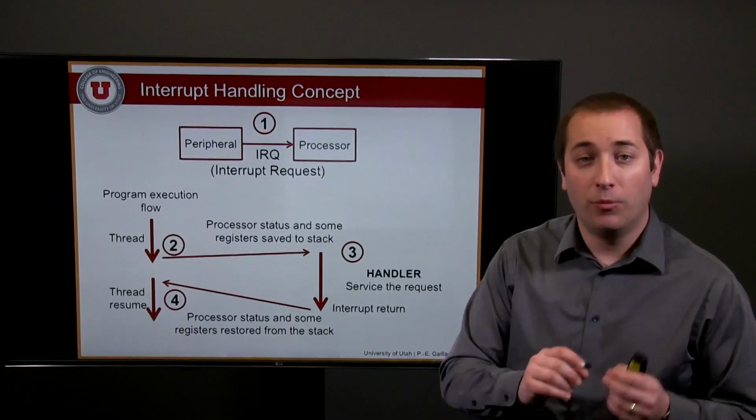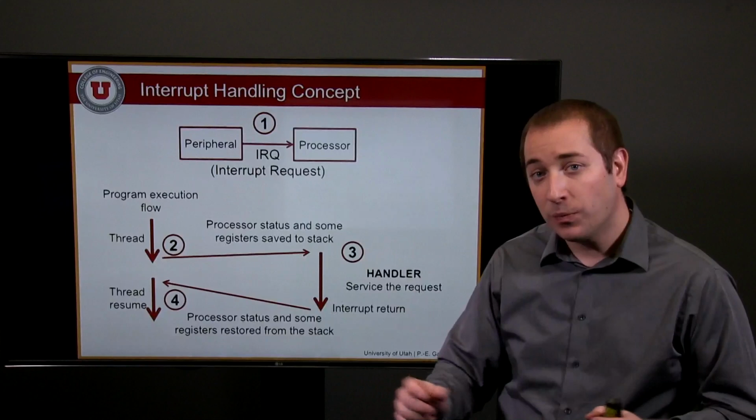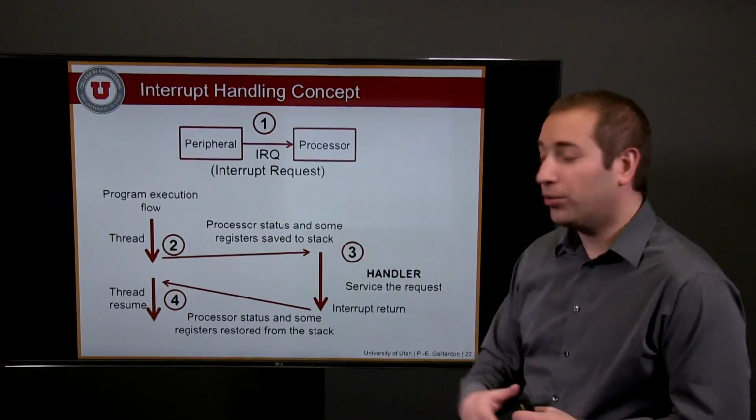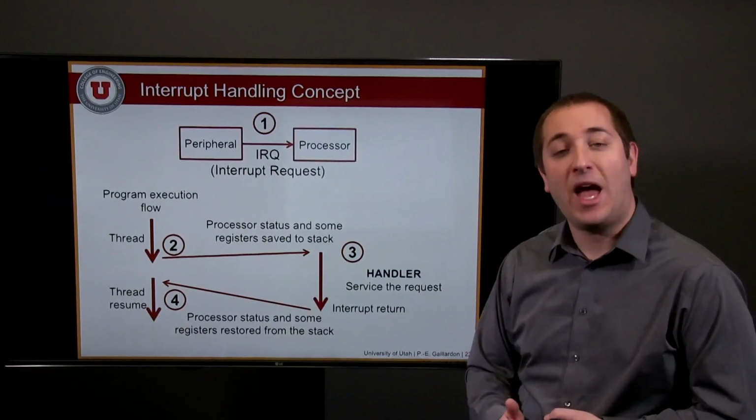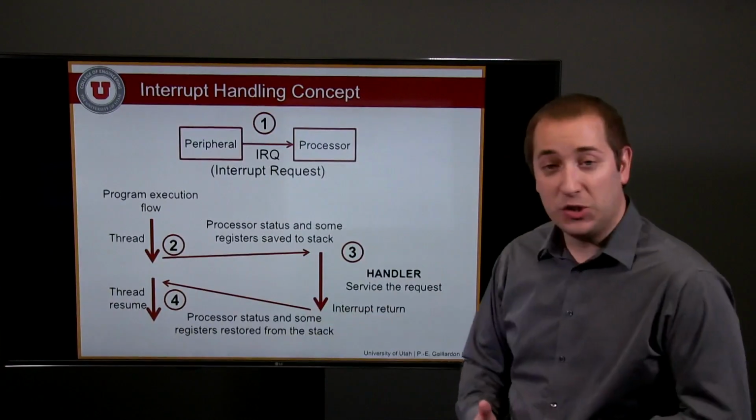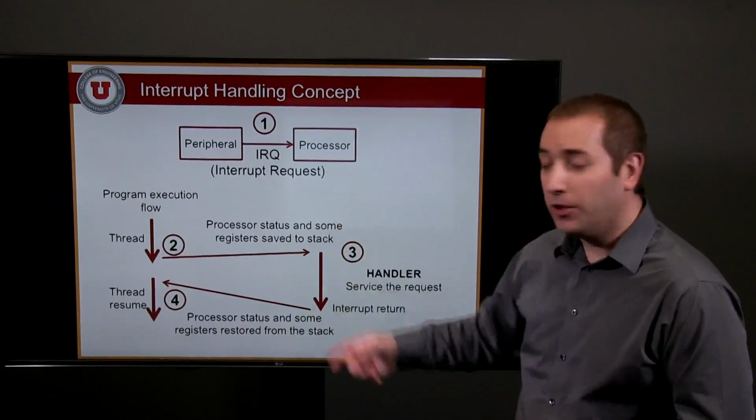In order to jump from the main thread into the handler mode, you need to implement some processor status and register save mechanism and restore them back once you're done. This is done through the stack.